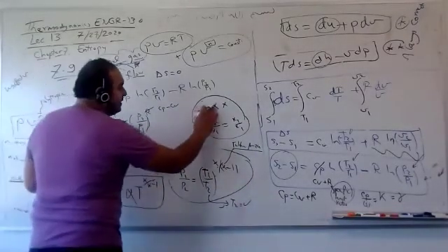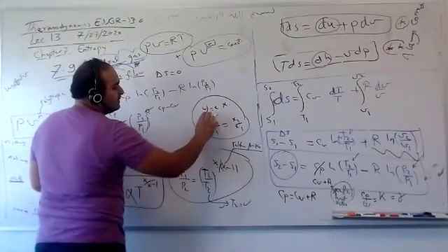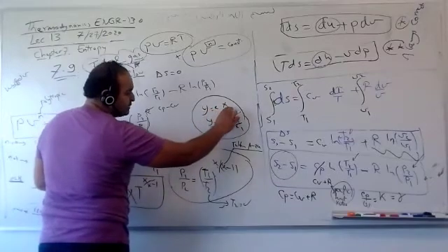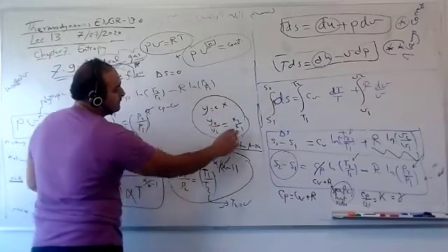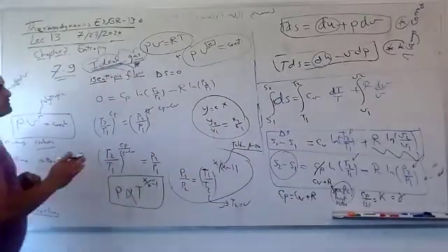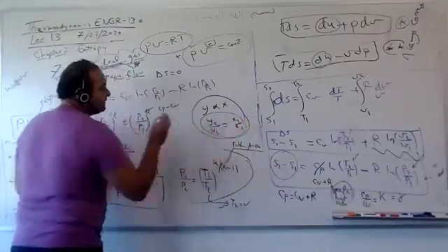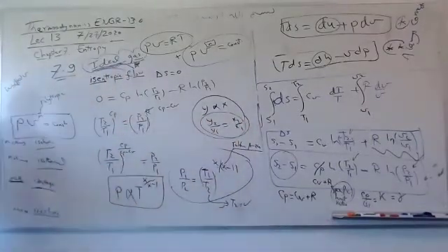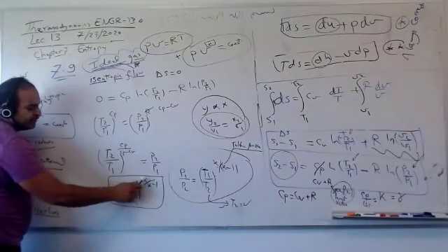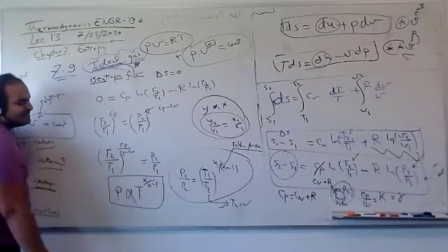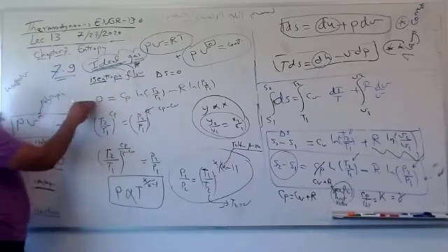So you can say either Y equals C times X, or Y2 equals C times X2 and Y1 equals C times X1. Divide, so C will be gone. This constant of proportionality can be removed if you use ratios, like here. So pressure is directly proportional to temperature to the power K over K minus 1. K is the specific heat ratio. And we derive it: delta S equals 0.